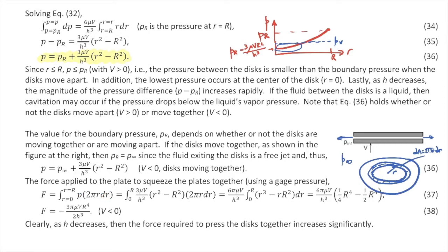By the way, I'm writing out the pressure force in terms of the gauge pressure. I don't have the P infinity here because you'd have P infinity acting on the bottom, and so they would cancel. So I'll just work in terms of gauge pressure, so that's 0 gauge pressure out here, and on the interior I just get rid of the P infinity. So I can substitute in for P here, assuming a gauge pressure, and I'm left with that term.